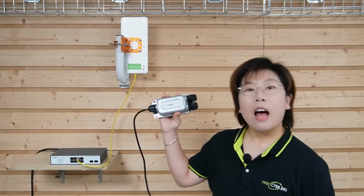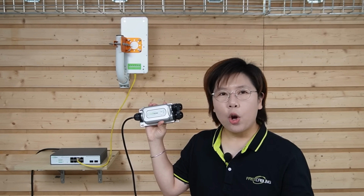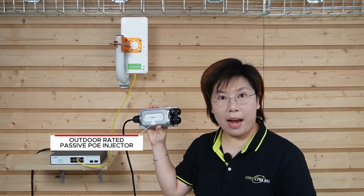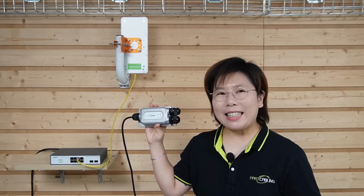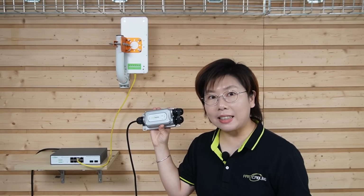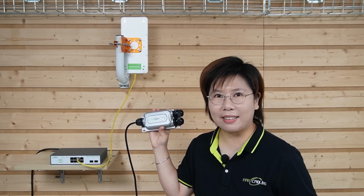We need a passive PoE injector, but not the cheap plastic ones. We need one that can survive up on the mountain. So this is our outdoor rated passive PoE injector. This little box is simple. It takes data from your router or switch on one side and power from a standard outlet on the other. It then combines them and sends them out over a single Ethernet cable to your device.